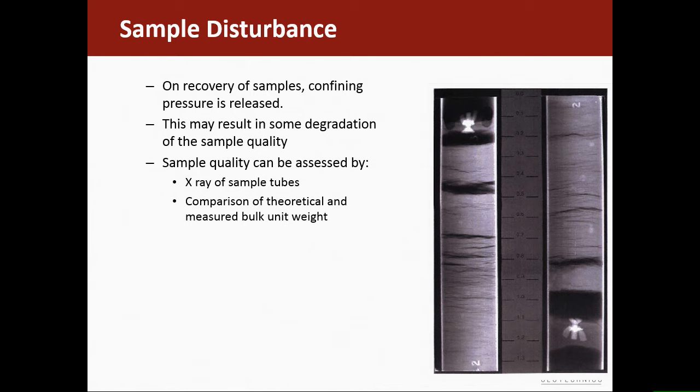But you can see you don't really want to take that part of the sample because there's water or something's happened there. You'd be much happier taking that or that section of the sample to do your testing on, so you've got really undisturbed clay, truly undisturbed clay. And you get much more reliable results, obviously, if you've got undisturbed material.